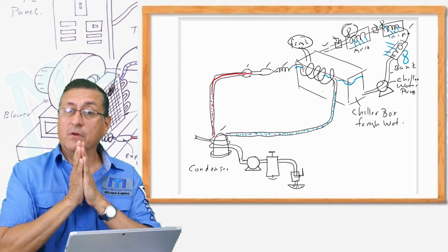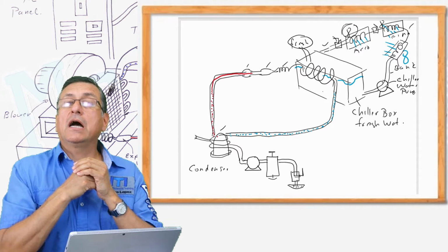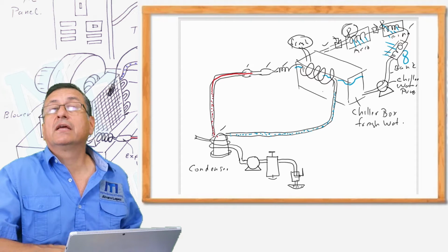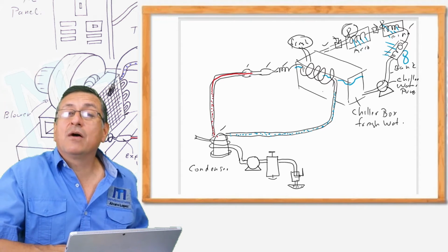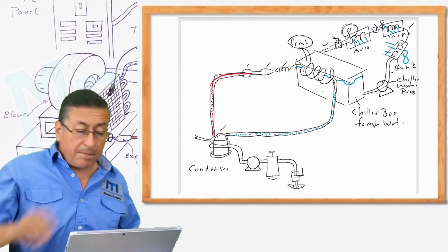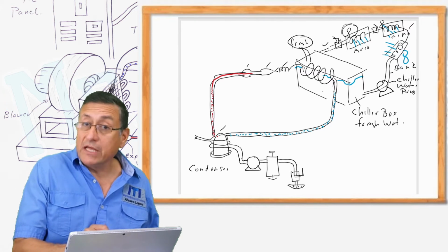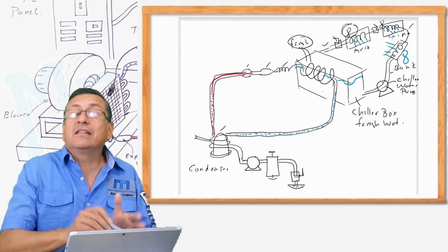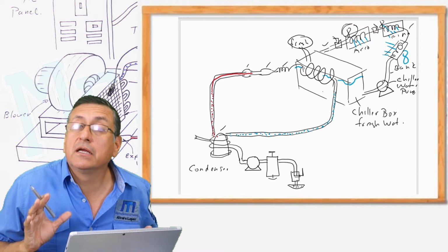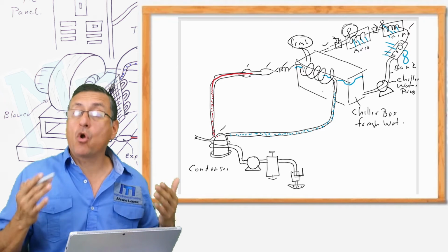Danny Ramirez, one of my former students, is the second engineer on that boat, and he disconnected the traditional raw water system and connected the cooling tower, because the boat is out of the water. Remember that to connect the cooling tower is too simple, because the condenser in this traditional chiller system is working in the traditional way. The coil of the condenser is cooled by raw water.